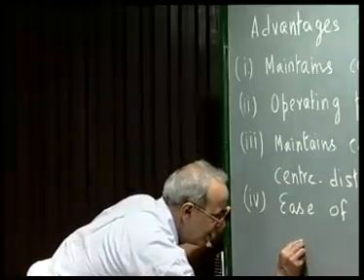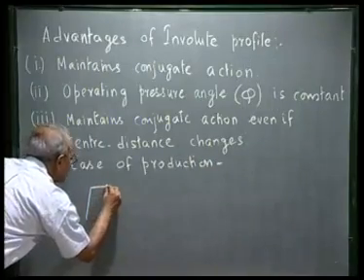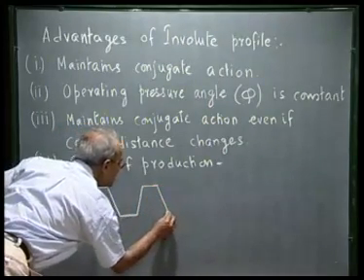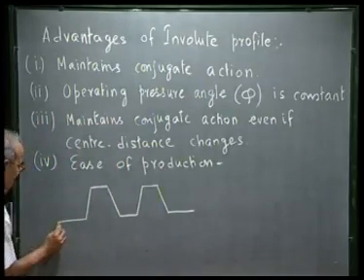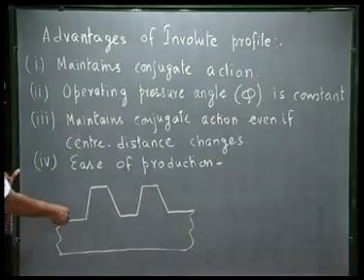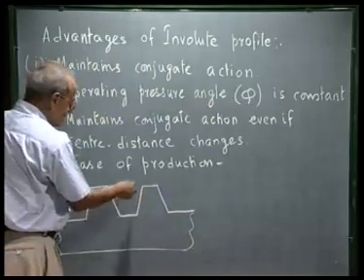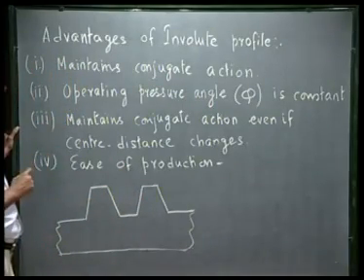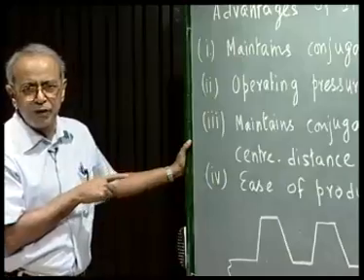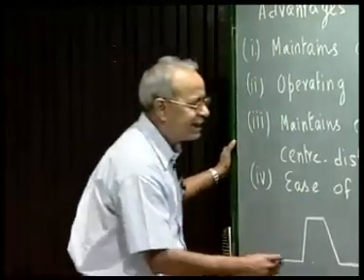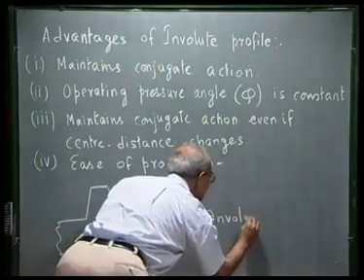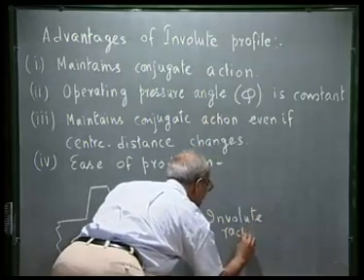If we have an involute profile, we will see this later, that the conjugate rack tooth, if this is a rack whose tooth profile is straight, then it can maintain conjugate action with an involute gear. And it is such a straight sided rack cutter that is used to produce the involute tooth profile on a circular gear blank. I can say it is an involute rack, which is used as the cutter,